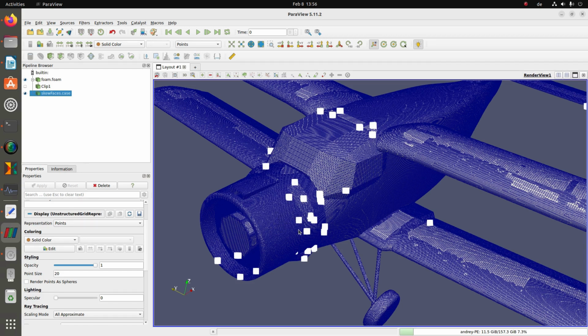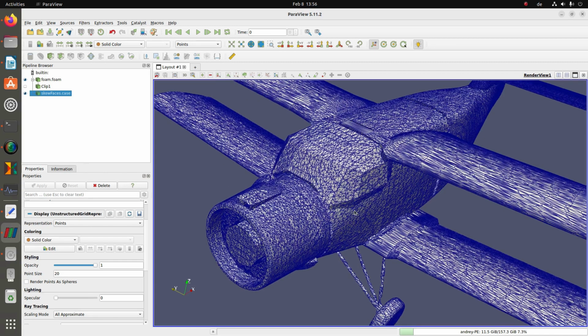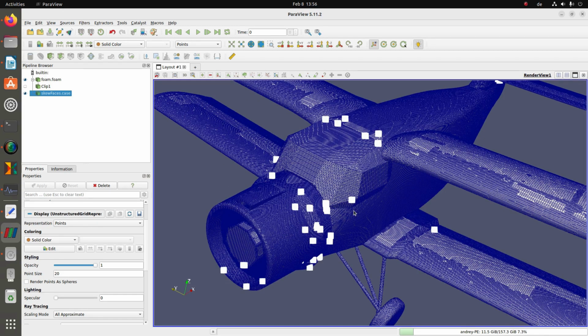For example, my Excel tool is able to export the settings for good or best mesh quality. Now, I do not do this because I think that the calculation can also cope with this mesh quality. Only when the results deviate, I do the settings for a good quality.